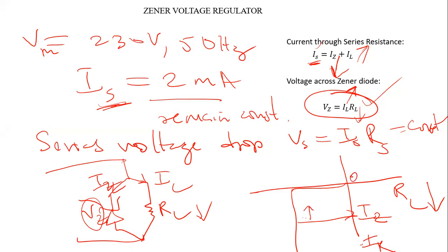This is your 0. Okay, reverse current is in the negative axis. This is your reverse voltage VR. IZ value will drop down from, let's say, here. Initially in the example we have given that IZ value was 1 milliampere. Now in order to compensate for the decrease in the resistance, IZ value will drop down to, let's say, 0.5 milliampere, something like that. Okay, so when IZ value drops, IL value will be raised, and then IL into RL will remain constant.